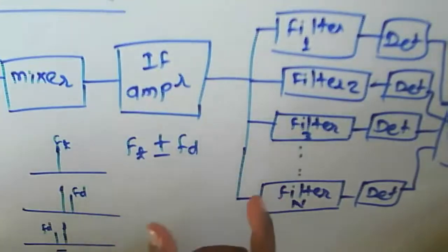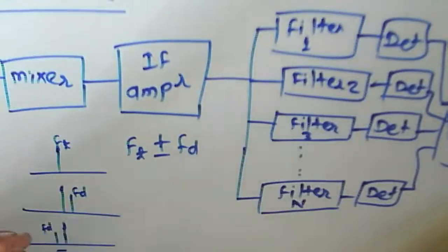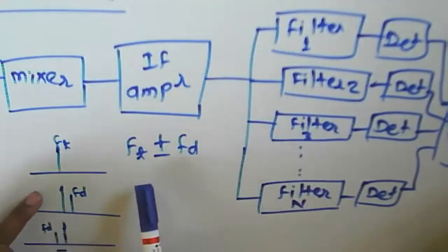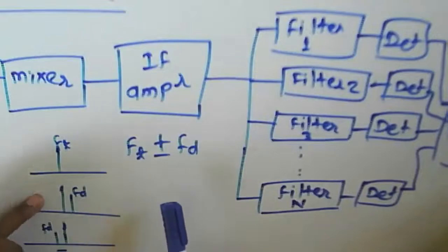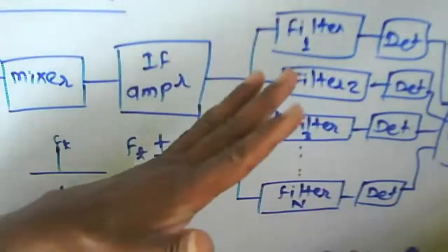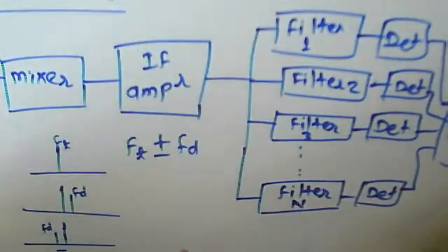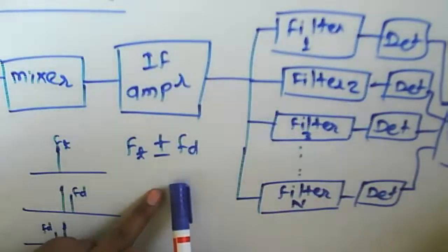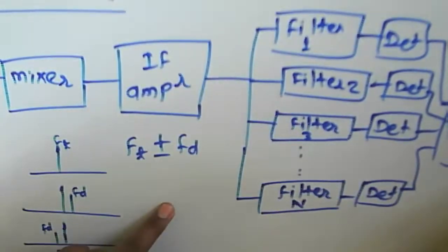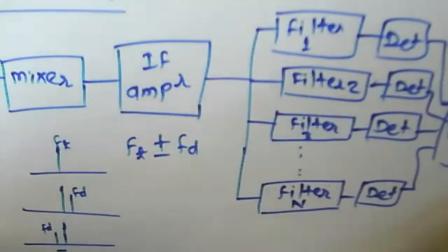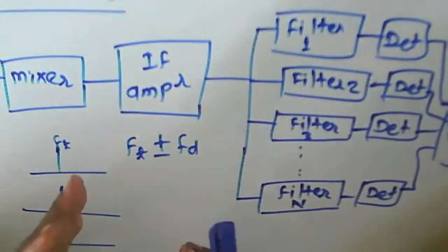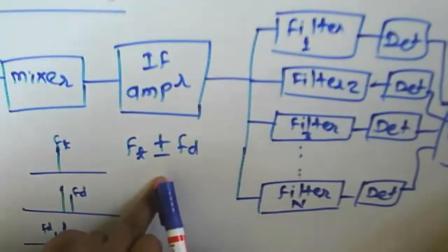Okay, for a given particular spectrum, whether it will be forward or backward is again not satisfied using this particular technique. To get the plus or minus fd, we would have to use that much of a bank of filters. So instead of that, we can consider in which direction your signal will be, whether plus fd or minus fd.